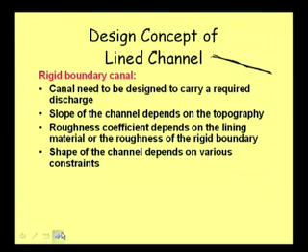In fact, for improving the channel carrying capacity, many a time the side slope of the canal, the sides of the canal and the bed, are lined with some finer lining, so that we can have better flow through that. Well, then another aspect is the shape of the channel, which depends on various constraints. Of course, I am not writing it very elaborately. Now, what can be those various constraints?